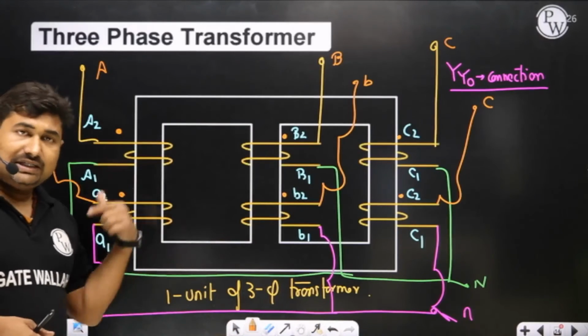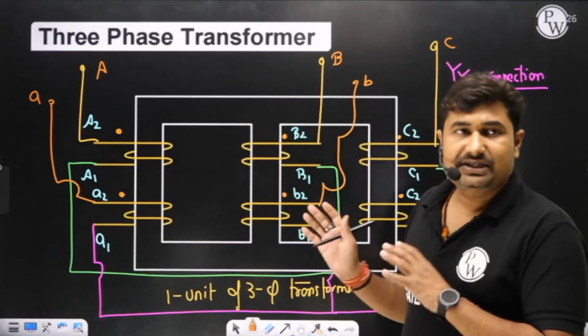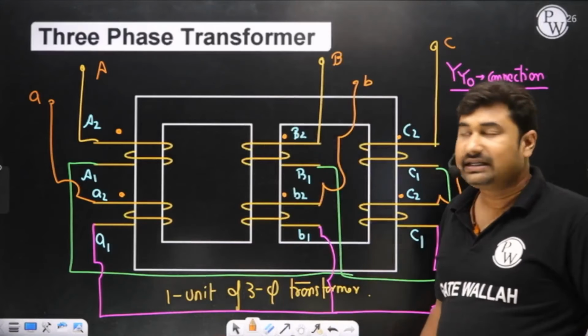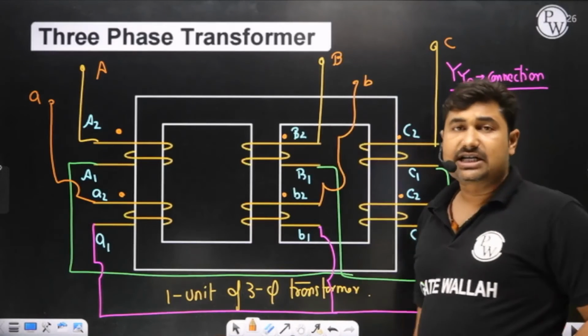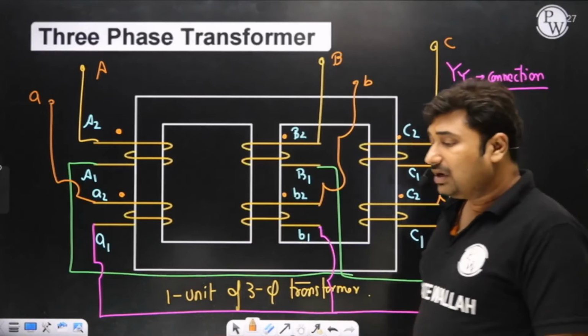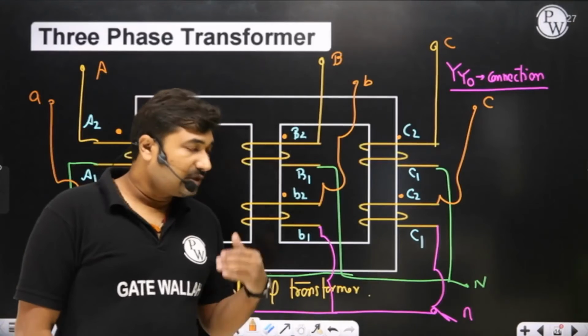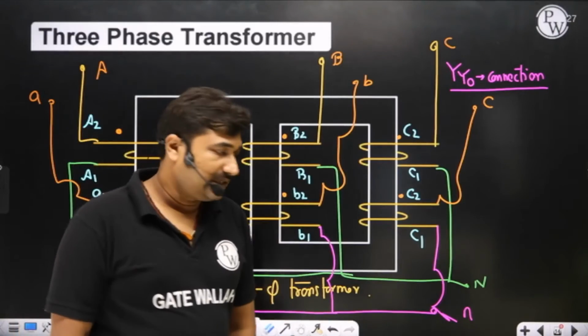So once the connection is designed, we can't change the connection. In case any one of the transformers gets faulted, then the entire unit is unable to work, or unable to transfer power. Is it okay? Yes, sir.